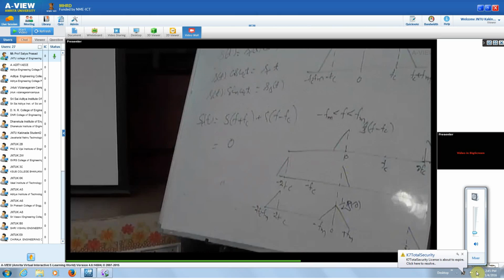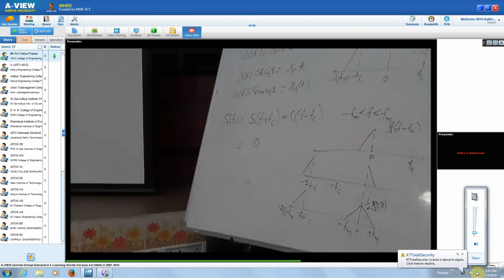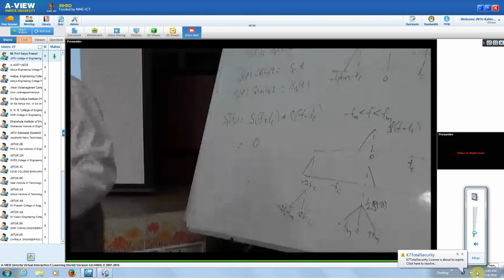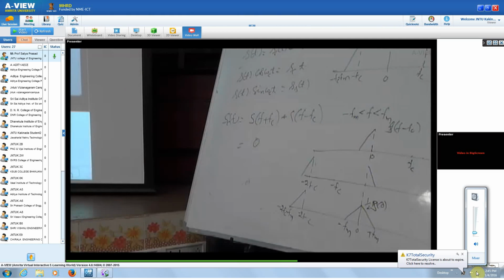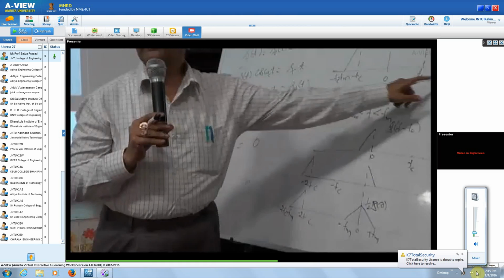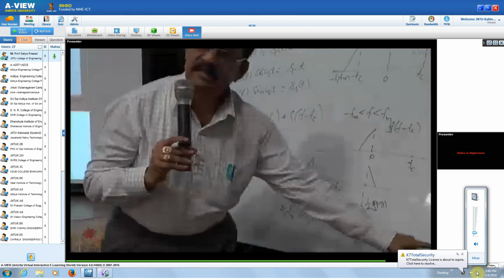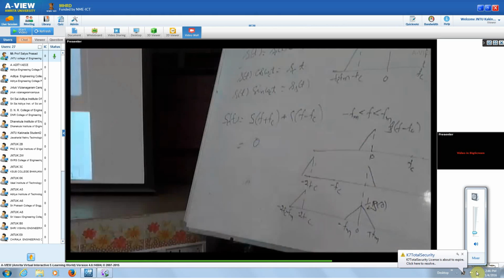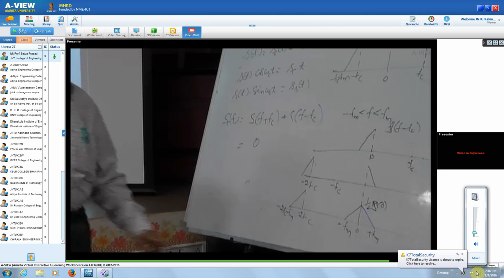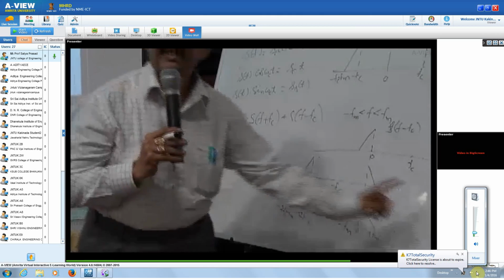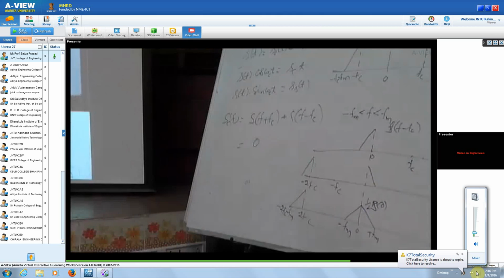Minus FM to plus FM. And what is this? But with a carrier of 2FC. Right? This is the SSB signal with a carrier FC, whereas these two lines correspond to the SSB signal with a carrier of 2FC. By passing through a low pass filter, only this will be passed through, eliminating these spectral lines.